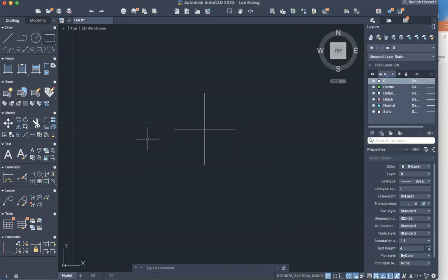Okay, so the next thing is to make the hexagon shape. We have the square or the rectangle, we have the circle. So what function should we use when we are making a polygon? Oh, sorry, hexagon. I already gave you the answer. So the answer is polygon. The number of sides is going to be 6, and then I'm going to specify the center of this polygon.